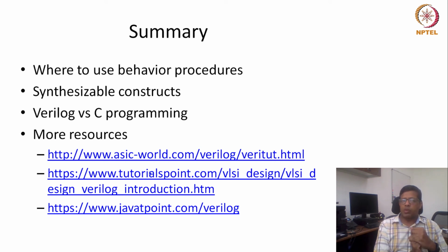The other disadvantage of using the behavior model without thinking much is that sometimes some constructs are not synthesizable. So finally, when we are going to design a circuit or synthesize it on an FPGA, in those cases it may not give the desirable result. We may be expecting, for example, a multiplexer, but it may design something else. So the cost may be different because we are leaving it to our synthesis tool to decide what to infer.